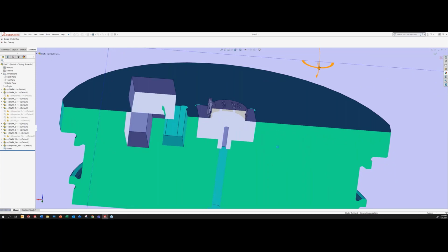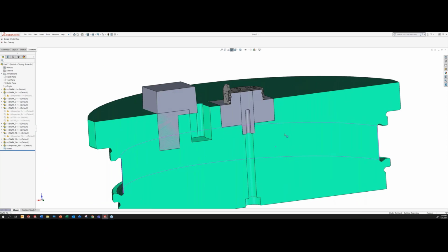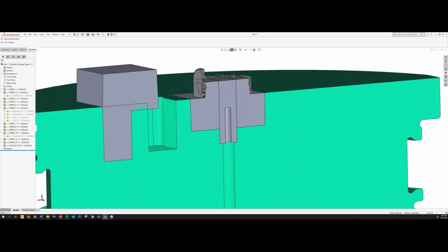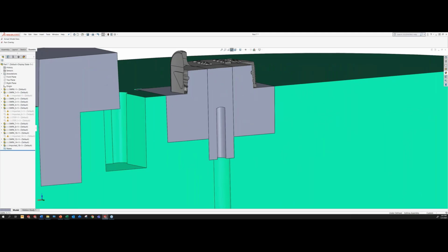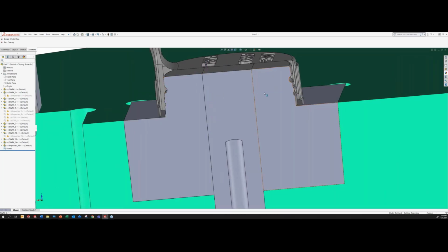And you mentioned the second cavity was made in case the customer wanted to make changes, but only steel-safe changes could be possible after the mold tool is made? Not necessarily. You can change out these inserts if they wanted to change the profile of something inside here.